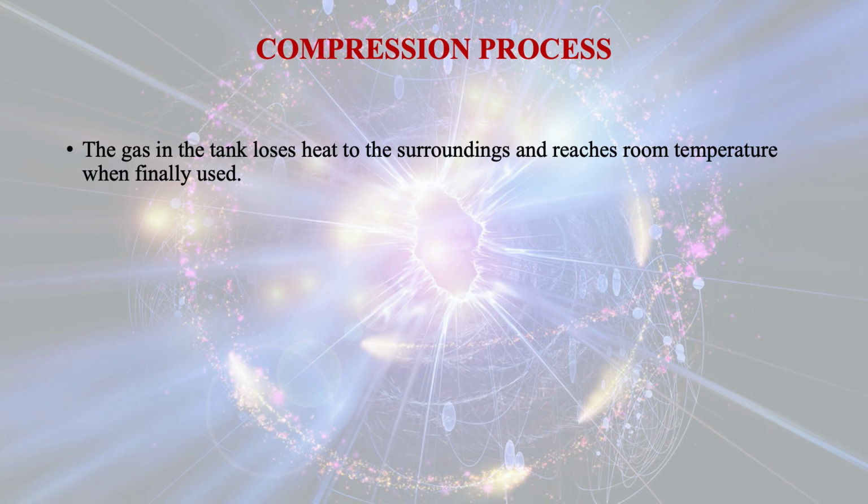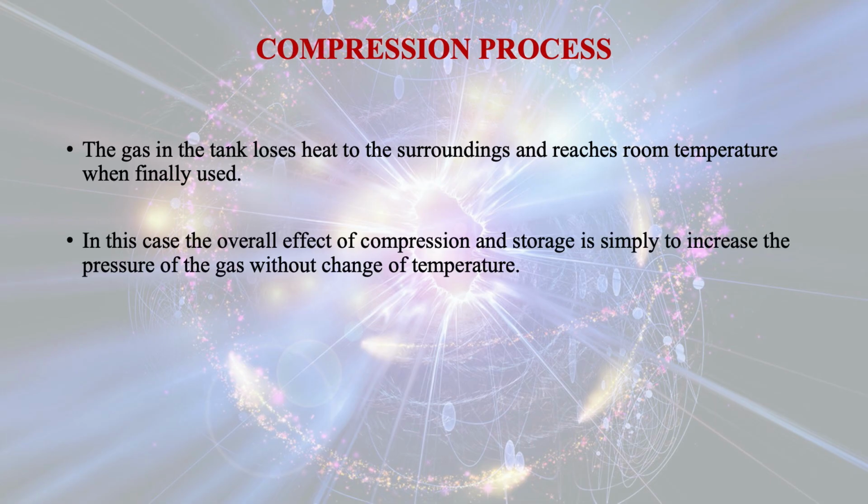Now we shall discuss the compressor for which the gas is not being used promptly. At a later time, generally we use the compressed gas. The gas in the tank loses heat to the surroundings and reaches room temperature when finally used. In this case, the overall effect of compression and storage is simply to increase the pressure of the gas without change of temperature.